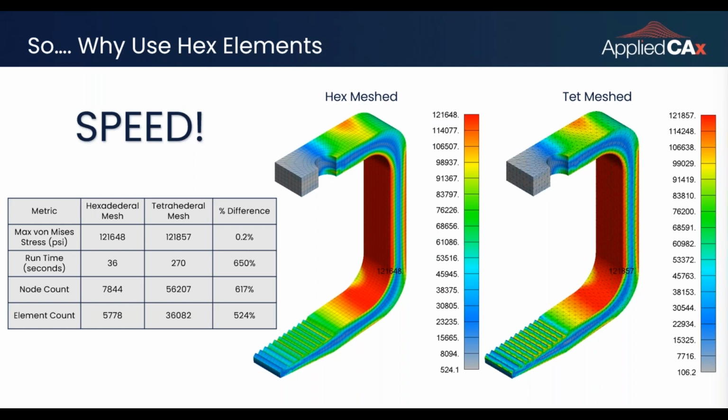And I could just add, if you do use that automated generation and then decide to keep your mesh uniform by making all of the hex elements parabolic, then you kind of lost the advantage of using that tool in that you increase the size of the problem dramatically by using the 20 node hex element over the 8 node hex element.